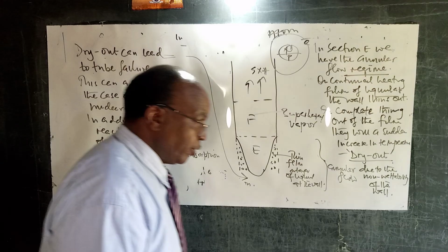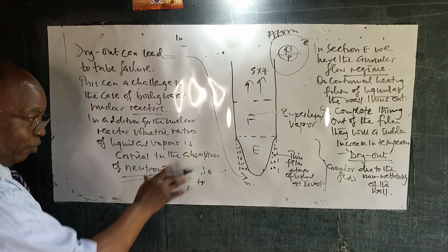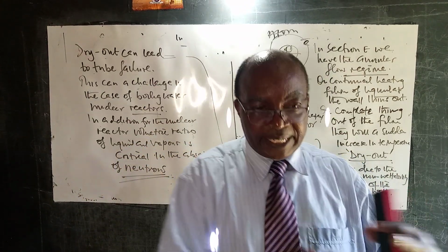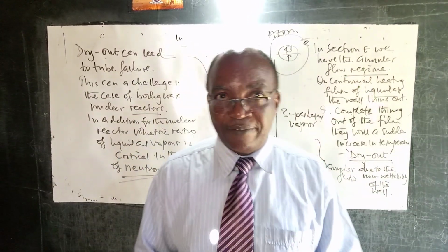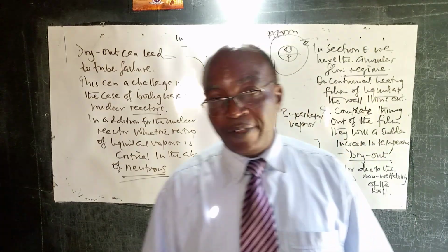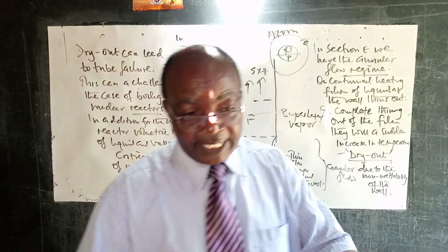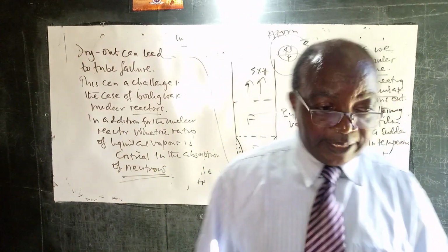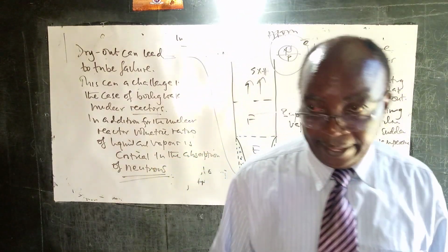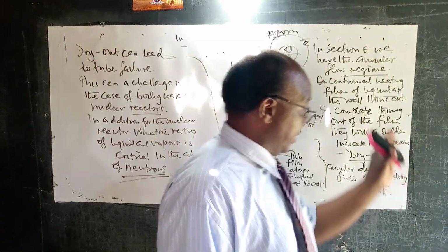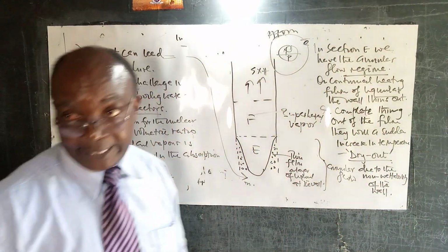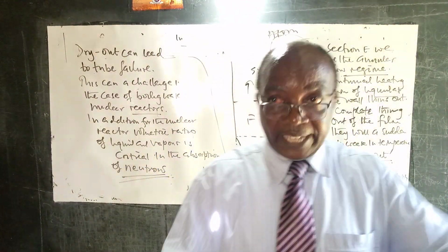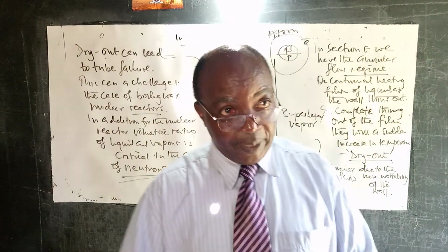And also remember that the non-wettability of the wall, which results in this sudden temperature rise, is partly a result of the very poor heat transfer coefficient. The heat transfer coefficient now is very poor when the wall is no longer wet, because the thin film is completely vaporized. And so we have that dramatic change in temperature, which actually brings in